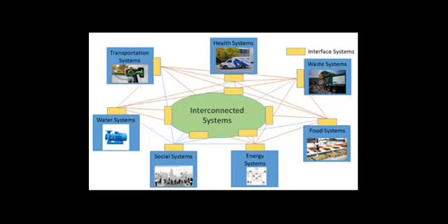Synchronization and phase alignment. For grid-connected systems, the renewable energy sources must be synchronized with the grid's AC frequency and phase. This ensures that the power generated by renewable sources is in phase with the grid power, avoiding instability and blackouts. Grid protection and control. Renewable systems should have protective devices to isolate them from the grid during faults or disturbances. Additionally, they should have control capabilities to regulate the power output and respond to grid requirements. Smart grid integration. Implementing smart grid technologies can enhance the integration of renewables. Smart grid features, such as advanced metering, demand response, and energy storage integration, can optimize the use of renewable energy and improve grid stability.